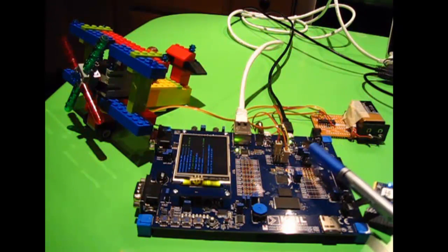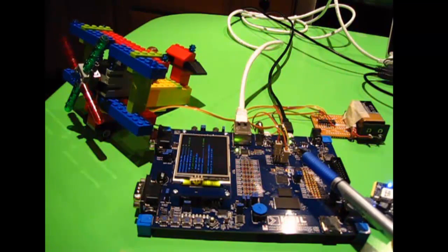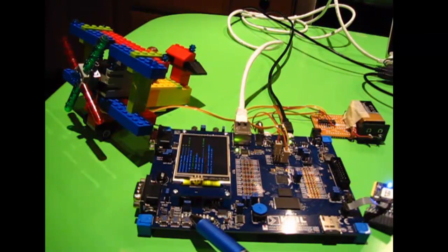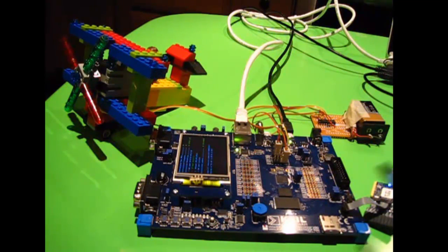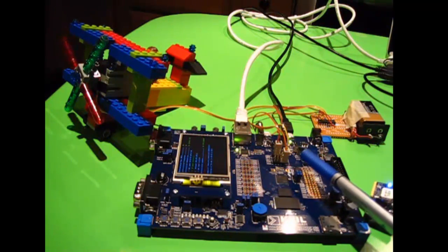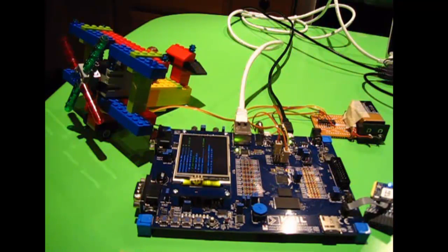Remember that these pins here, that is PH3 and PH7, are actually mapped to the LEDs. So what is going to happen is as the values in these pins go low and high, the LED will actually turn on and off depending on the value. So these LEDs are very useful for debugging and understanding what's going on with each of the GPIO pins. Okay, so as the airplane moves, we should be able to see the lights on the LED going on and off. So let's run.